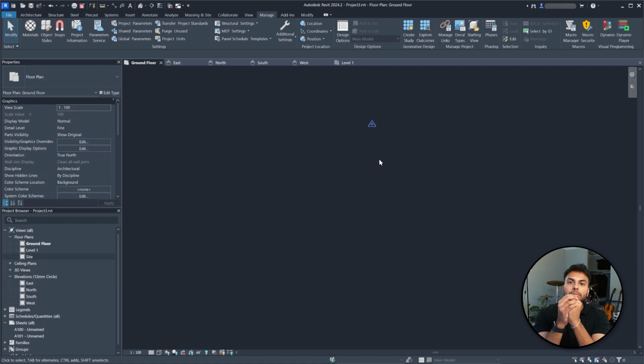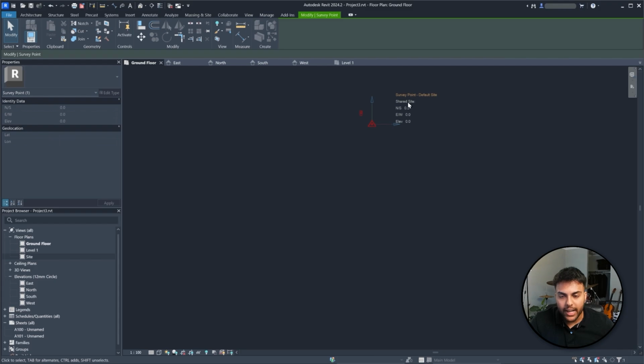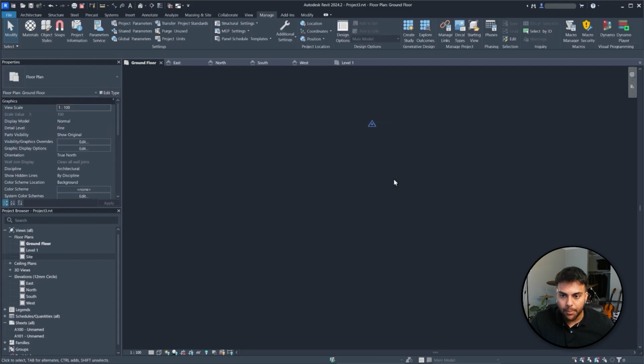Because I wanted them to be on the same position on top of each other, because then I knew, okay, from this position, you move this much up. Because before, if you have them misaligned, I don't know what the distance is between this and this, and I have to do some math calculation in order to move this, right? So that's why align them first, make everything 0, and then move the project through that command. What you'll see is your survey point actually stayed at 0, 0, 0, but your project's now missing because you moved it all the way up.